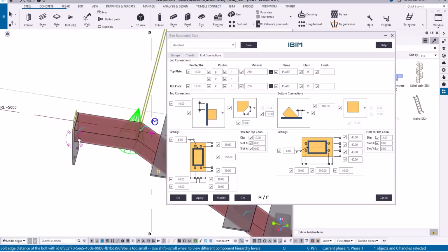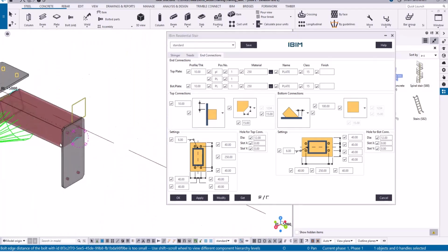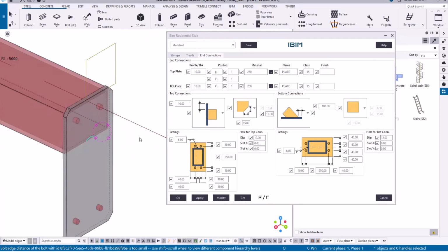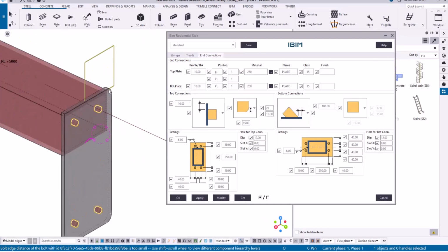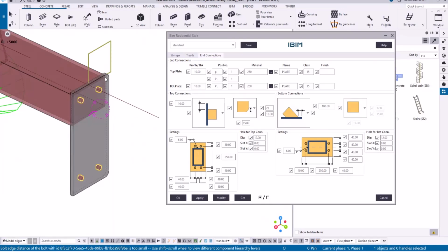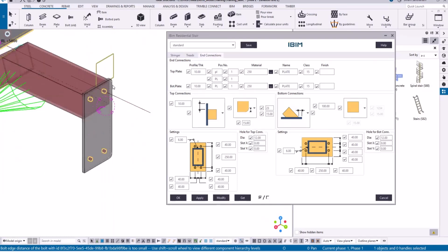And again, if you want to add chamfers to this plate, you can enter the distance here, and then I'll change this option to rounding. So now I type the corner numbers 2 and 3. So you can see the chamfer only on corners 2 and 3.